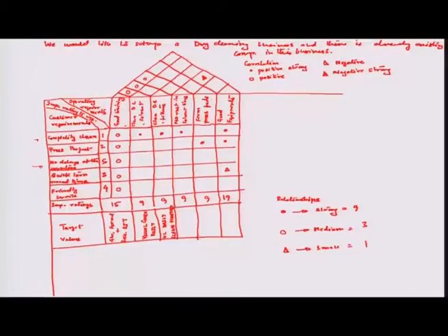For no rust in the lines, again we can have a visual check daily. So, we say this is VC daily. Again, for the firm press pads, we might be able to change the press pads on a monthly basis, so that there are no issues of movements or creases getting altered or spoiled because of such movements of the pads.